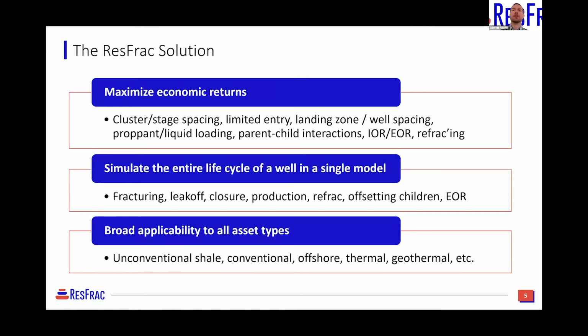ResFrac feels that in order to do so robustly, we need to be able to simulate the entire life cycle of a well in a single model. This is opposed to maybe some other solutions that have separate modeling software for separate phases in the life cycle of a well. In contrast, when you start a ResFrac simulation, it starts with fracturing, proceeds directly to leak off, then closure, then production, and then any late life activities that you have, such as fracturing other wells in the model or refracking your initial well, all in a single model. And in doing so, it preserves the realism of the solution while also simplifying the workflows.